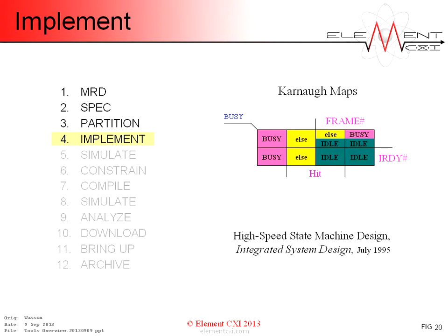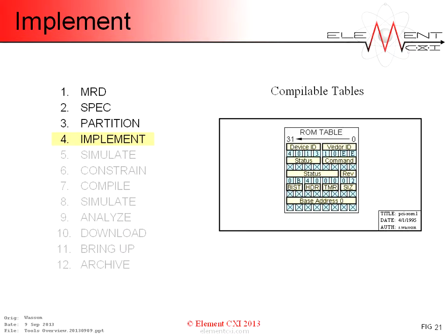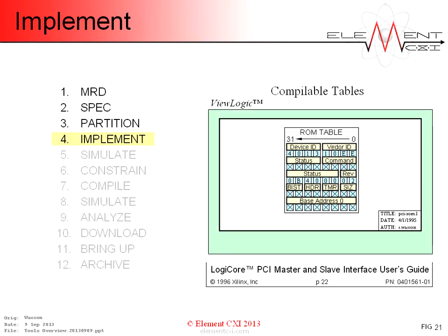features of value to the FPGA graphic toolkit. Another valuable graphic implementation tool is the compilable table, like this one, which I created in 1995 in ViewLogic for the PCI contract for Xilinx. Once filled in, the table performs a corner turn to slice out bits for ROM preload of each register.